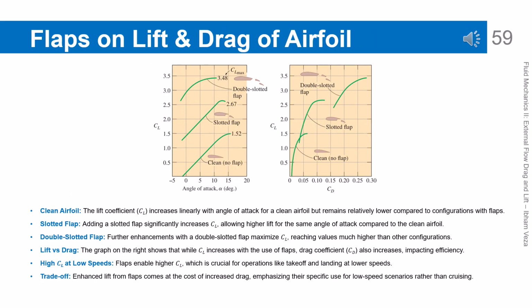Effect of flaps on lift and drag coefficients of an airfoil. A clean airfoil shows a linear relationship between lift coefficient and angle of attack up to near stall. By adding a slotted flap, the CL value can be significantly increased for the same angle of attack.